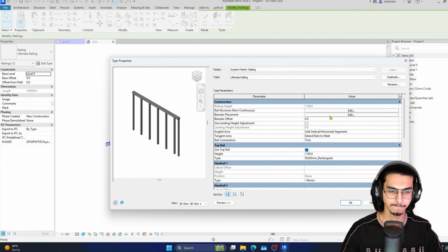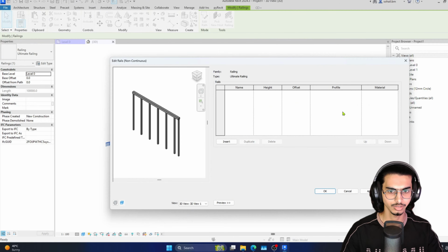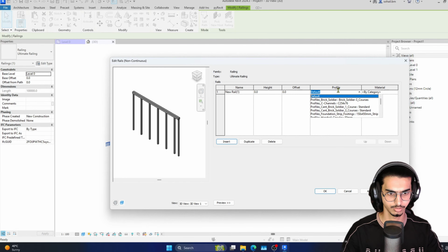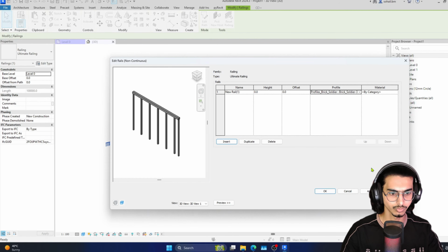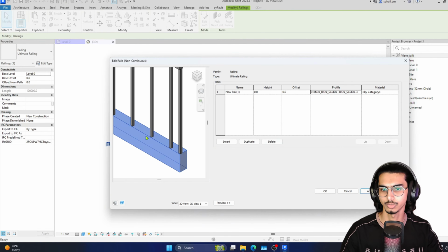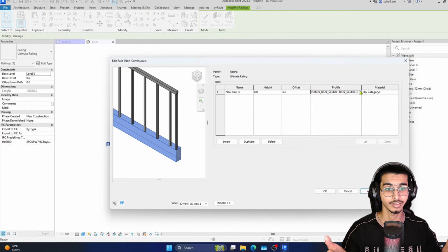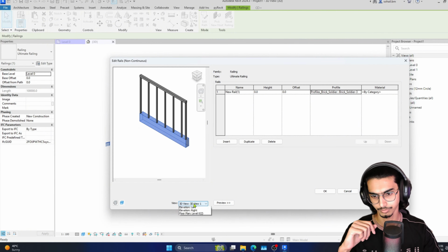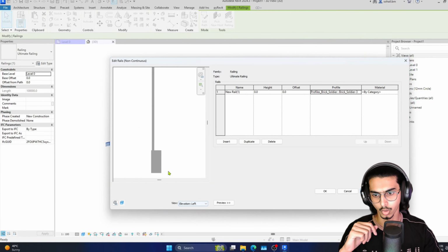If I show you, go into railing structure. If I insert any structure, this is going to use a profile. So if I make a break, apply, see, it is going to place a profile here. So this can be used to create your road base. Imagine this is your actual road.